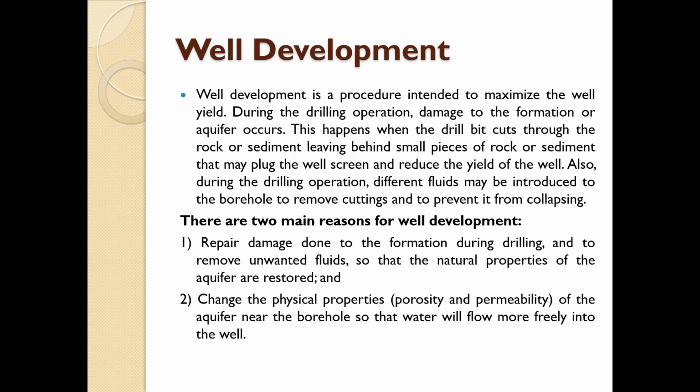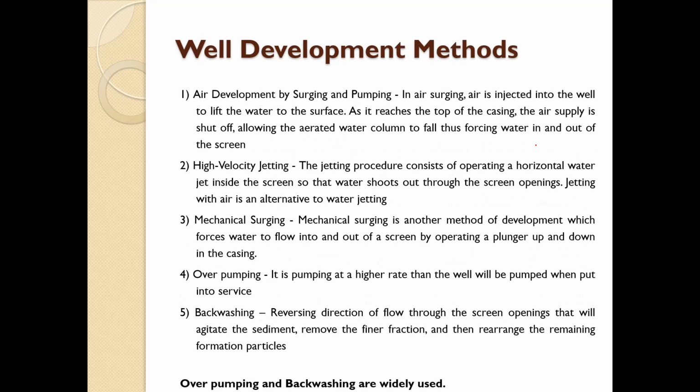First is to repair damage done to the formation during drilling and to remove unwanted fluids so that the natural properties of the aquifer are restored. Second is to change the physical properties, that is the porosity and permeability, of the aquifer near the borehole so that water will flow more freely into the well.